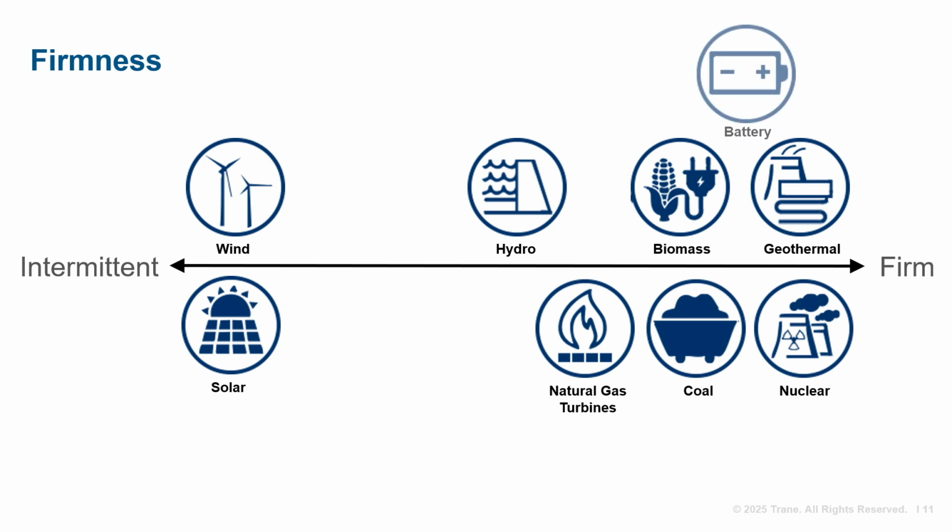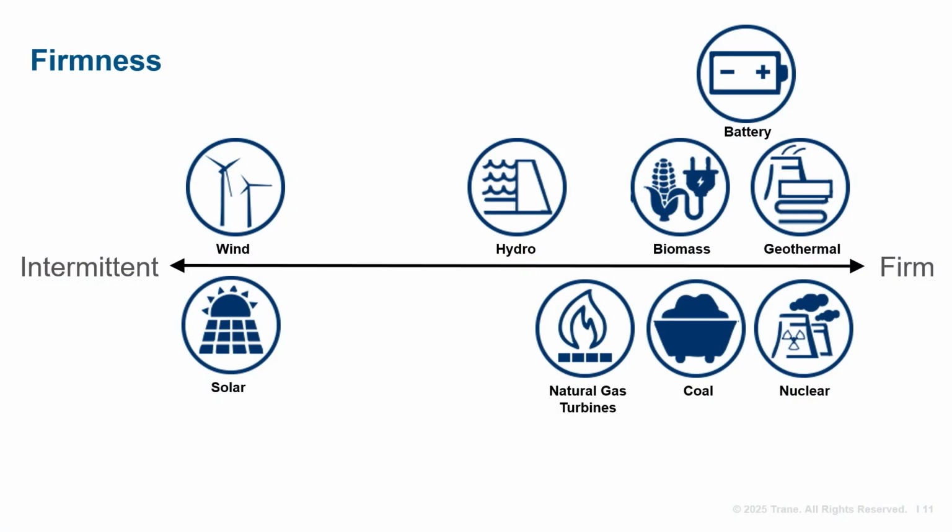very firm. As we discussed, energy storage such as batteries are important grid resources even though they don't generate electricity. An intermittent resource paired with energy storage acts as a firm supply of energy. So, for example, while solar generation itself is intermittent, if solar energy is produced and then stored in batteries, that power is firm. However, batteries differ from other firm resources in that they're not viable for very long-term storage. Whereas coal or natural gas can technically be stored indefinitely, battery energy can't due to self-discharge and loss of capacity over lifetime.